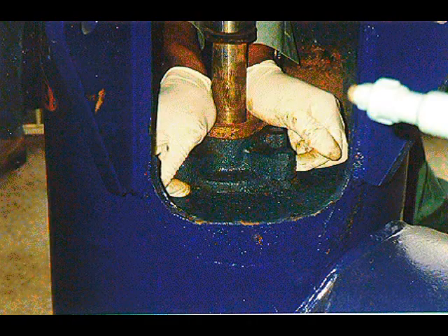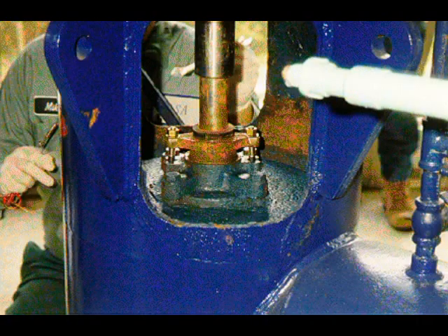When the lantern ring and enough packing rings have been individually seated so that the nose of the packing gland will reach them, individual tamping should be supplemented by the gland. After the last ring has been installed, hand tighten the bolts to very slightly snug. Do not jam the packing into place by excessive gland loading. Gland bolts should be tightened evenly.